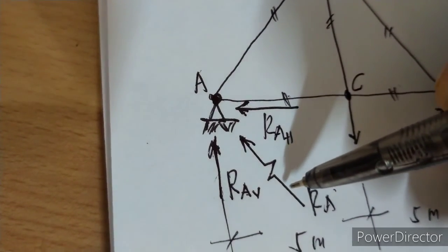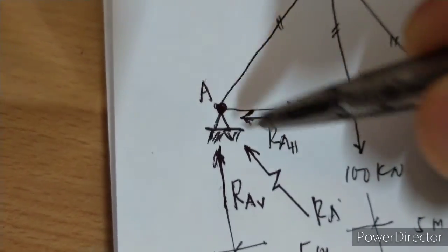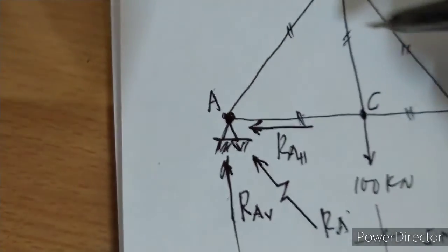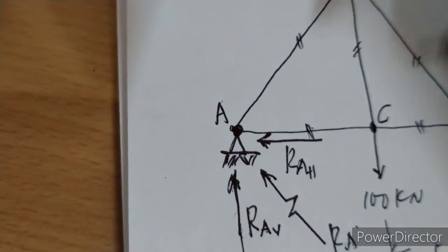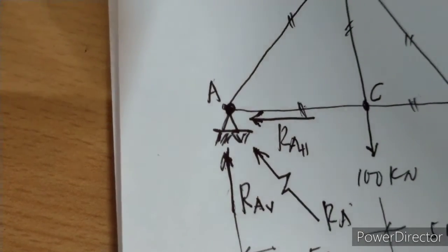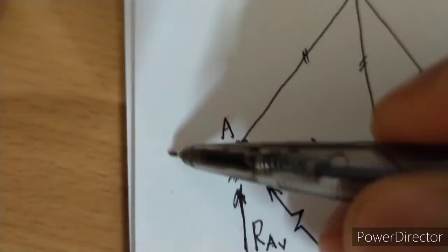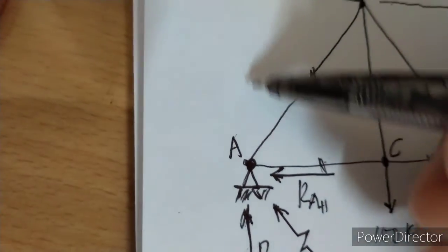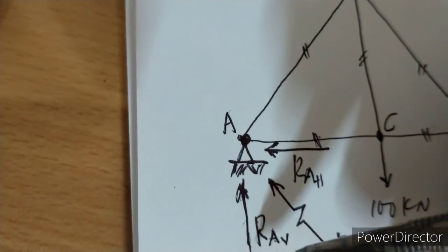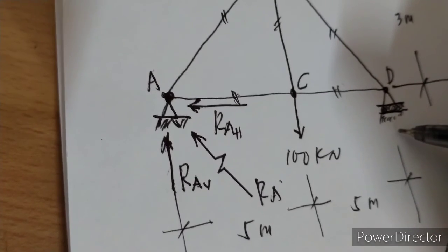Unless otherwise required, you are going to solve this, then you indicate it. But if it is not, in analyzing joints, we just simply need horizontal forces and vertical forces along the x and along the y. Okay, so in here at joint D, since this is a roller,